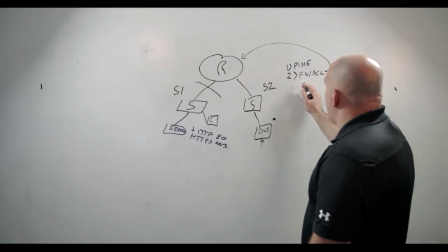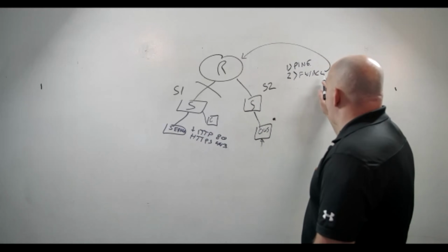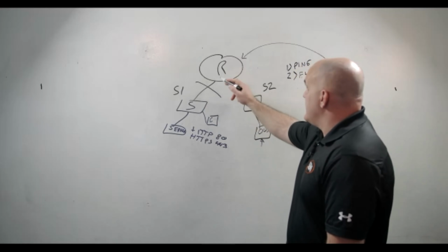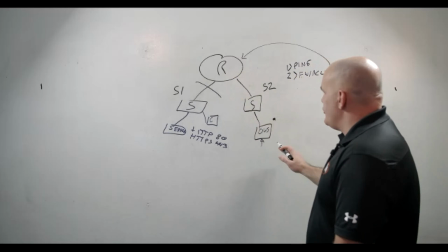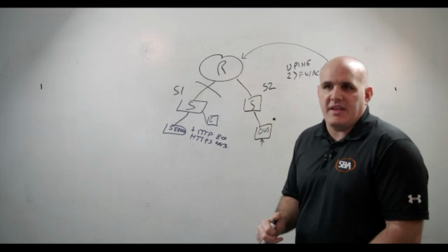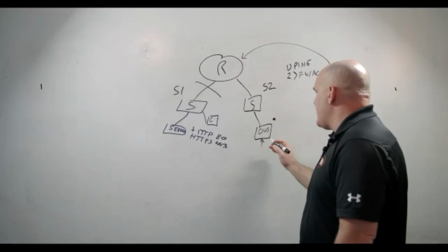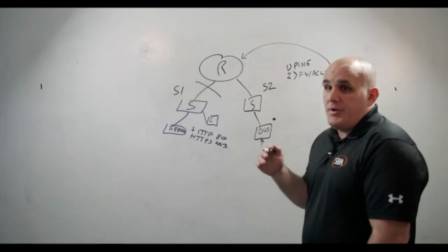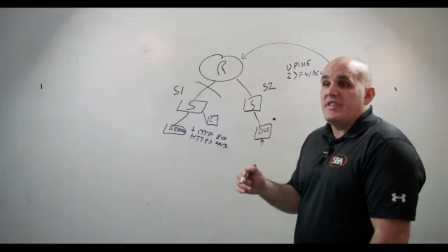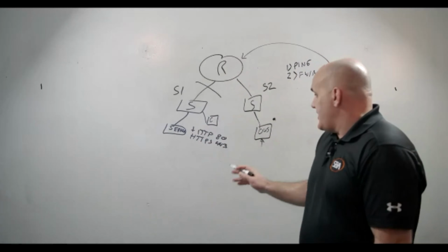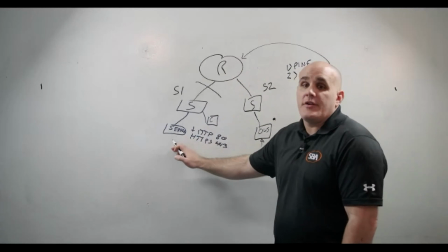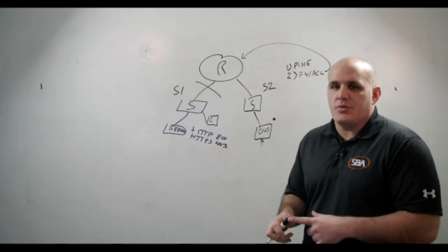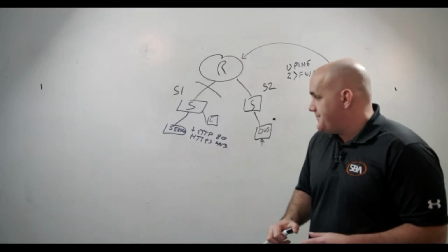Because remember, right? We checked ping, we checked firewall, we checked firewall ACL with our device over here. We ruled out that it was an issue right here. So now we're getting into troubleshooting the application. What I like to do here is say, okay, if I'm able to log in to the BAS application from my operator workstation to the server, then that tells me it's most likely the user's password or their administrative account.